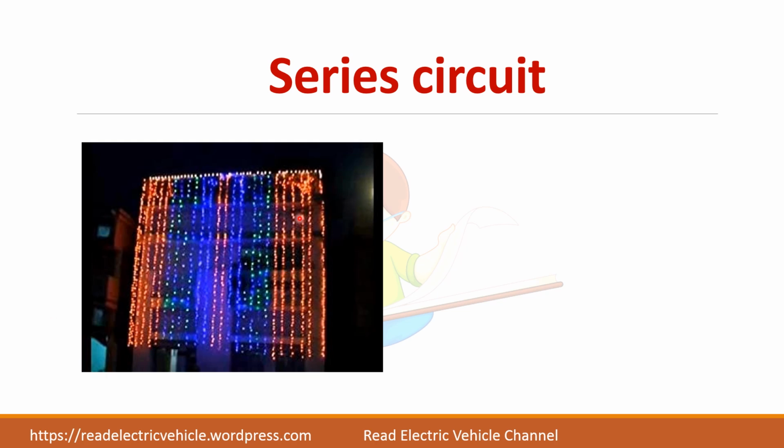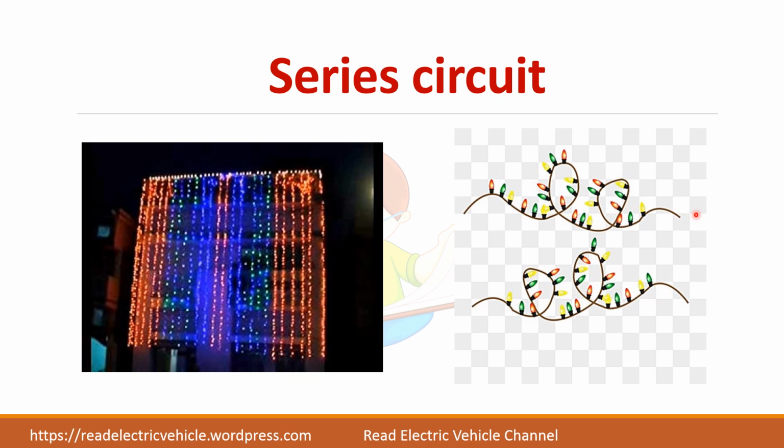The best example is the serial bulb. The same current flows through all the bulbs. Same current will flow. But the problem is that whenever there is a break or some open, none of the bulbs can glow because in an open circuit current cannot flow.